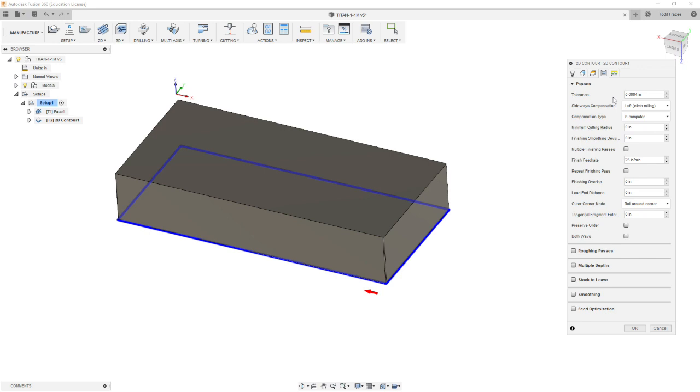On a modern CNC machine, they're very tight tolerance in their movement, and you can climb cut, which produces a better finish with most cutters in most materials. There are some exceptions, and generally you only climb mill with a CNC machine. If you were using a manual machine, you have to conventional mill almost all the time, or you can have the screw backlash and damage the machine.